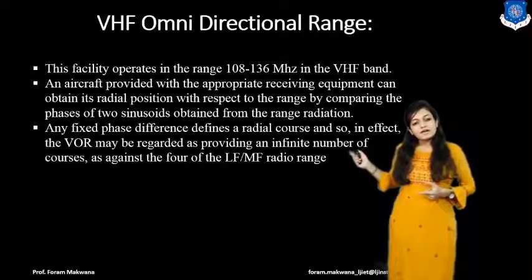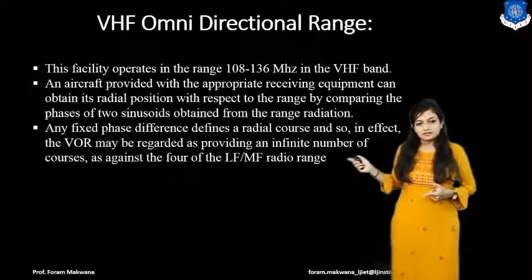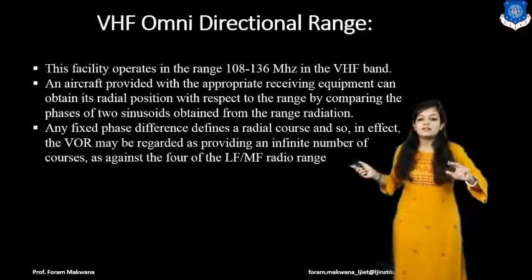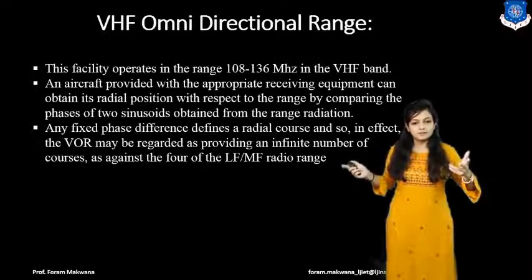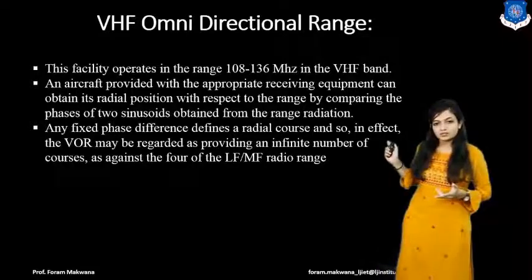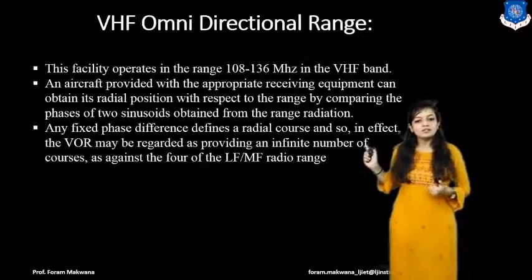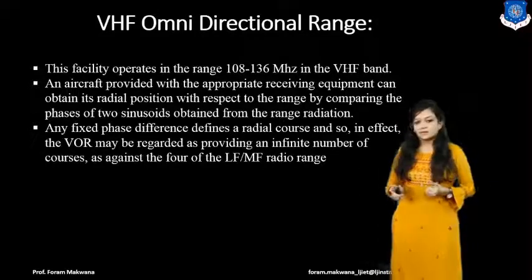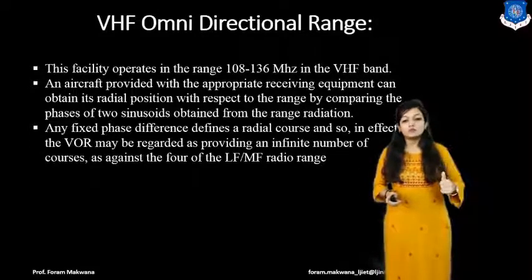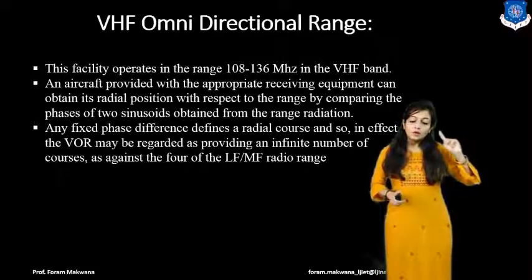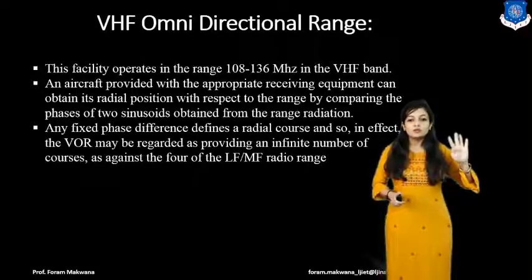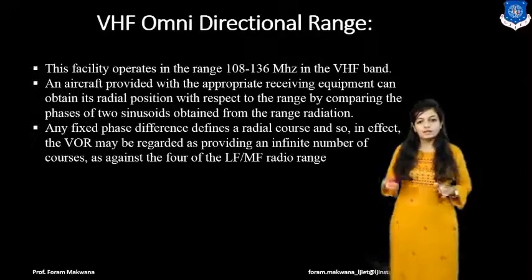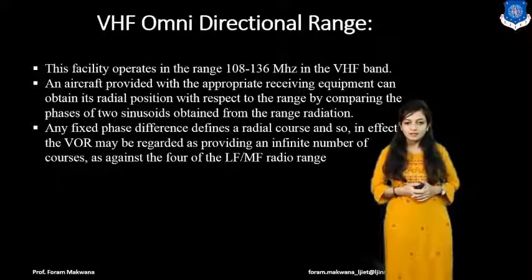But if there is any phase difference, what does it mean? It defines the radial course, and in effect the VOR may be regarded as providing an infinite number of courses. In low frequency, medium frequency, there are only 4 courses. But over here, infinite numbers of courses are there, right?